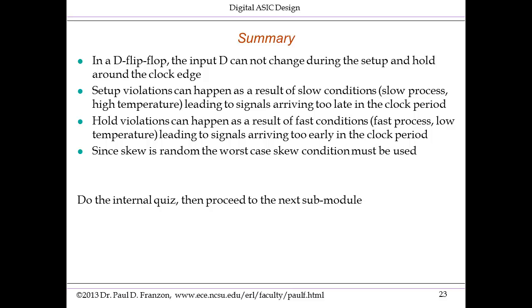So that brings us to the end of this submodule. I remind you of the main points here. In a D flip-flop, the input D cannot change during the setup hold period around the edge. Setup violations are the situation where the clock period is too slow in comparison with the longest critical path under the slowest conditions, leading to the signal arriving during the setup time or later.